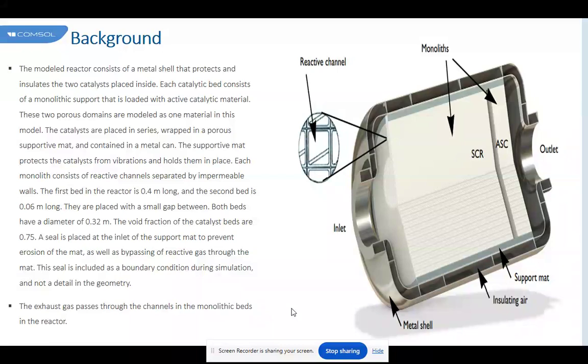Conclusion and discussion. As stated in the introduction, the main goal of this work was to investigate the effect of the substrate material on the steady-state and dynamic behavior of the catalytic monoliths. If the objective is to operate the monoliths in the region of multiple steady states and on the ignited branch, then we have shown that monoliths with high conductivity substrates, metallic and/or high aspect ratio diameter to length, lead to the ignited branch at lower inlet gas temperature, typically between 60 to 100 degrees centigrade.